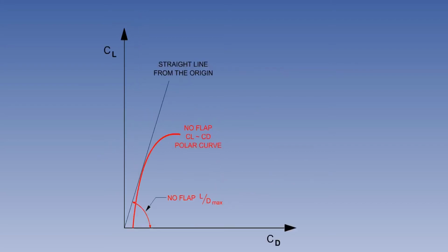Please remember that any amount of flap will increase drag. We have already seen that CLmax increases as the flaps are lowered, but unfortunately drag will also increase, so we need to consider LDmax. We must generate enough lift to balance the weight, but at the same time, drag must be a minimum. Therefore, drag will divide into lift the maximum number of times. We call that LDmax.